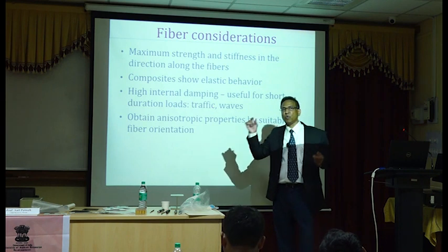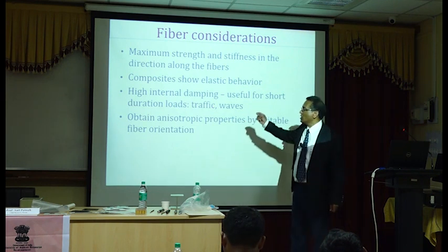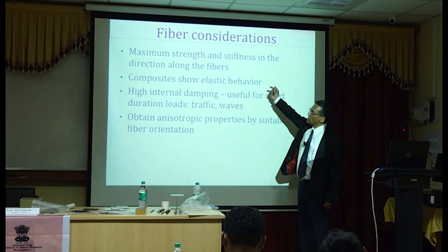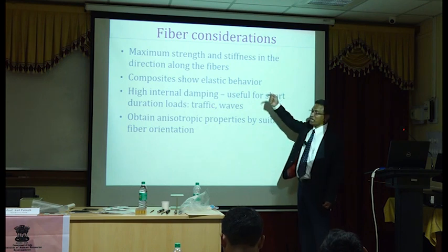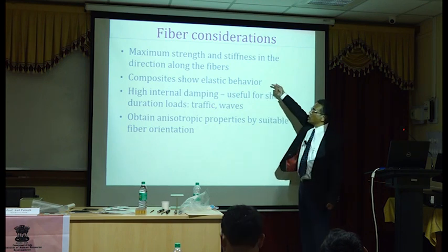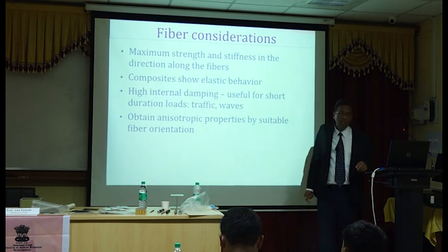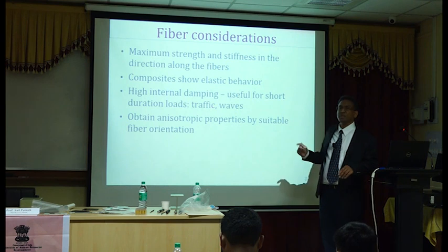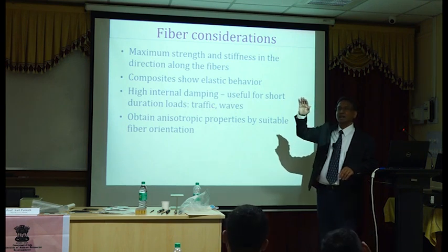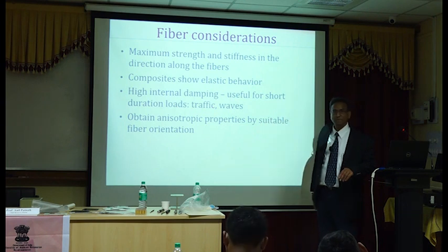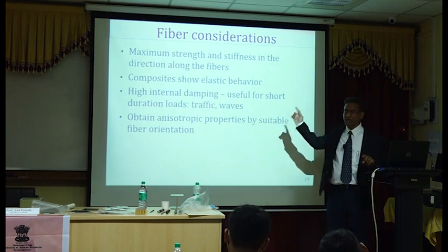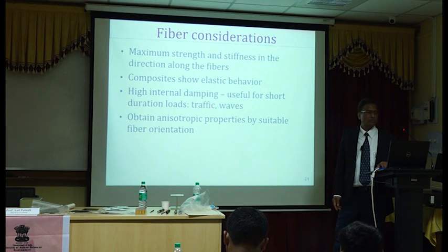So you don't know when that point is coming, and therefore very large factors of safety are included in all these design guidance to somehow prevent this kind of brittle failure, which is because of the linearly elastic material property. Does it make sense? We'll talk about it. It will be more clear when I present the stress strain curves.